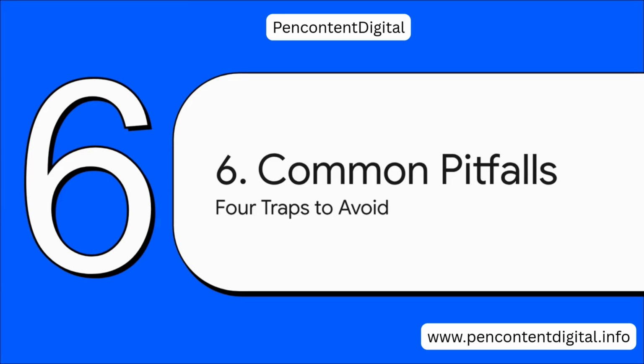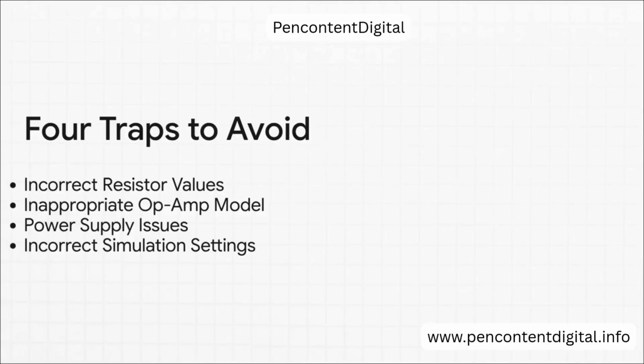And finally, let's go over some of the common traps that can really trip you up when you're just starting out. Think of these as pro tips to keep your simulations running nice and smooth. First, seriously, double-check your resistor values. One little typo can throw everything off. Second, make sure you're using the right op-amp model for the job. Third, and oh my gosh, this gets everyone at first, don't forget to connect the power supply to your op-amp. It's not going to work without it. And finally, make sure your simulation settings actually match the signal you're trying to analyze.